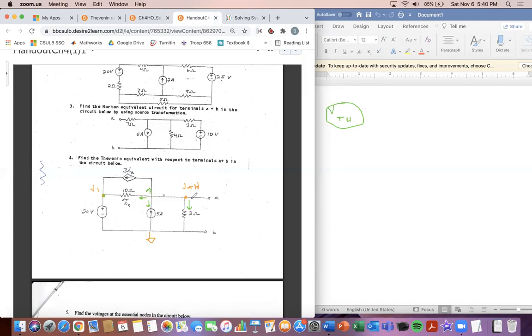So V Thevenin minus 0 volts here divided by 2. So that's a simple one. V Thev divided by 2, because we'll just simplify V Thev minus 0 over 2. And then this arrow going down here, we notice there's a current provided. So the current's going in the opposite direction of the arrow going out of V Thevenin. So it's going to be negative 5 amps here, minus 5 amps. And then what's going to happen here is we're going to have V Thevenin minus V1 over 10.